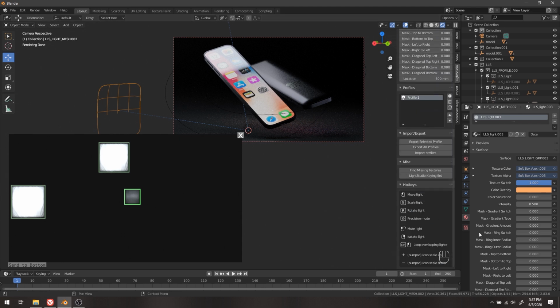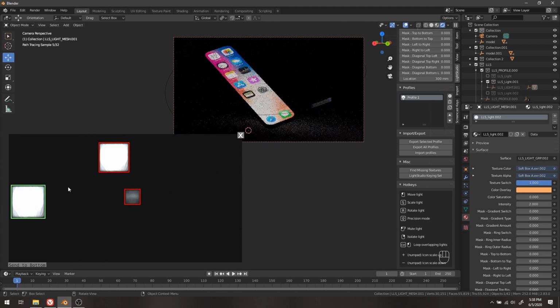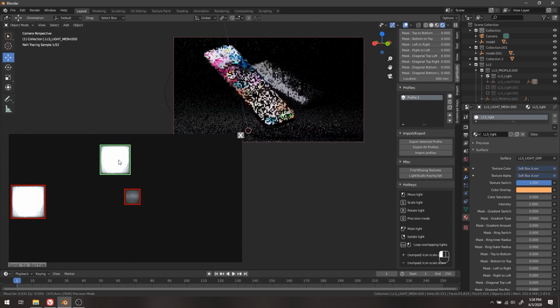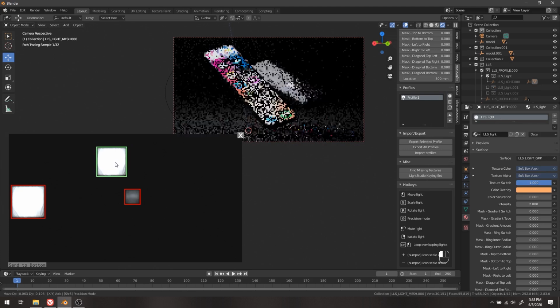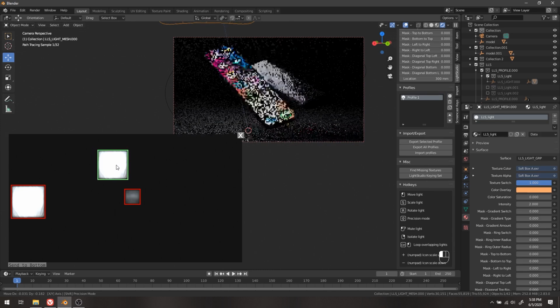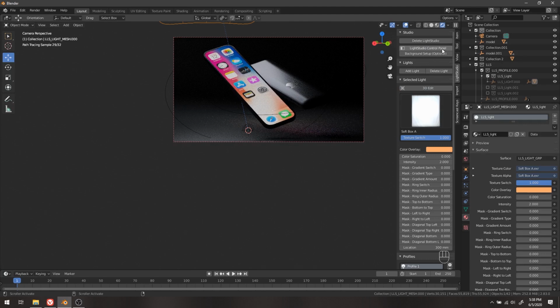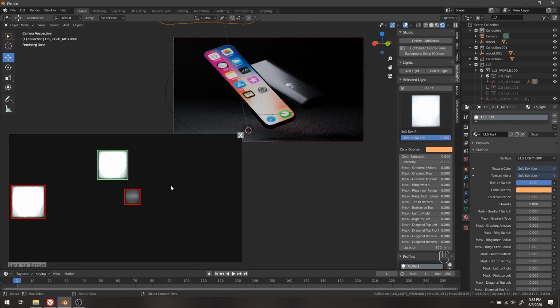One nice thing about this is there's a few different hotkeys that this lets you do. One of them is isolating a light with right click. So I'm going to figure out which light is giving me that. It's that backlight. So maybe lower it here so we don't have to worry about it. Just dismiss the dialog. And then you can just double click to re-enable it.